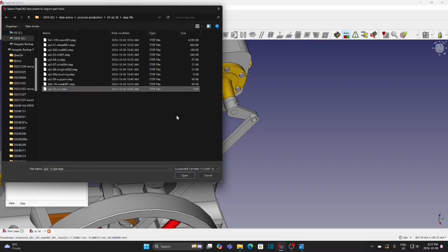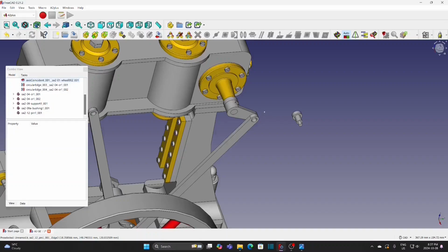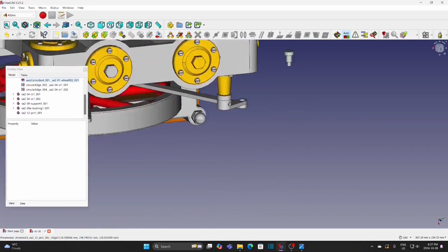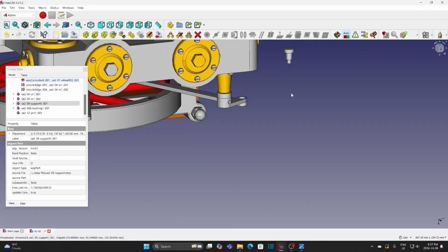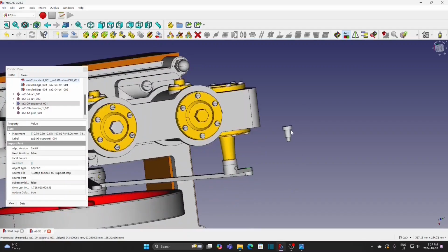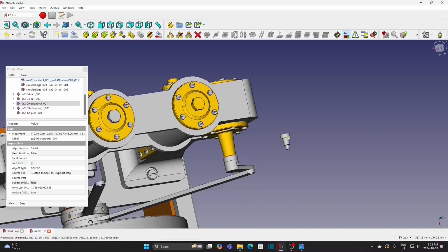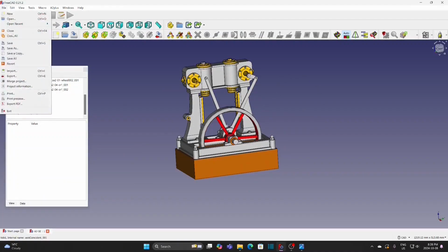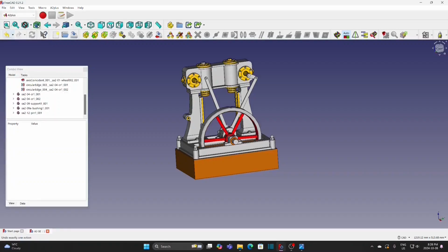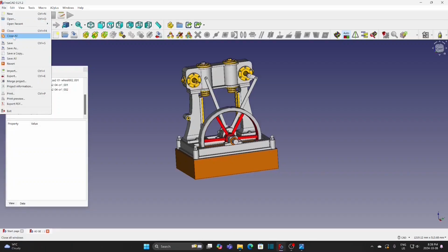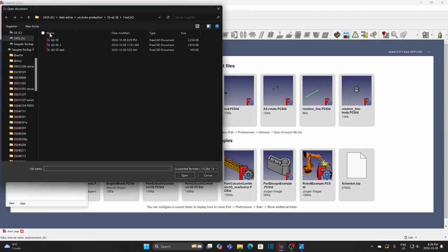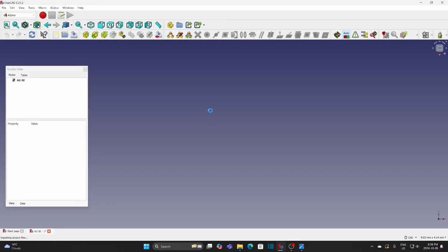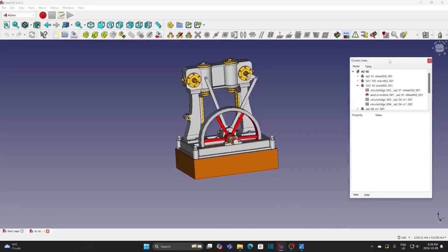Add the pin. Select these two circles and apply circular edge constraint. Save and close the file. We open it to update the file name in the system. As in my other A2Plus video, I just create a simple macro to do the animation.